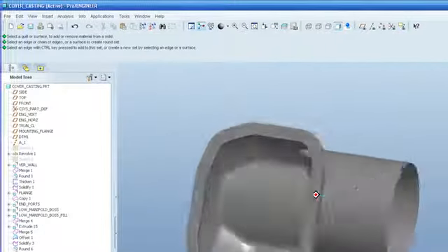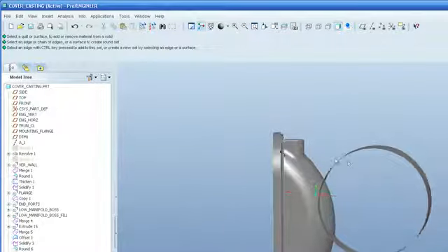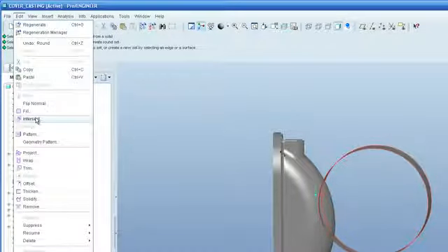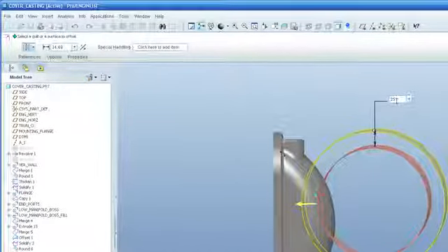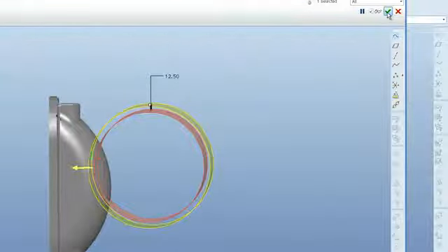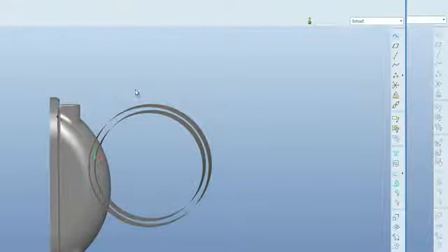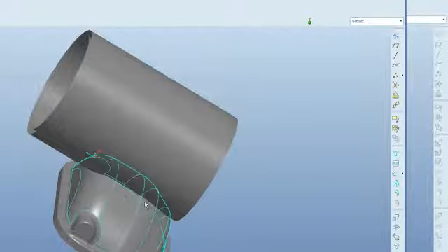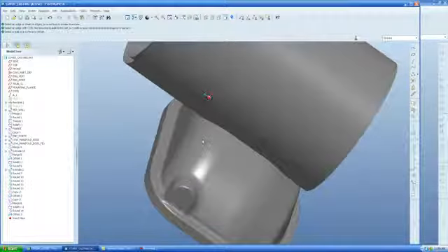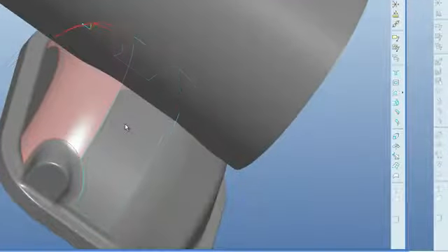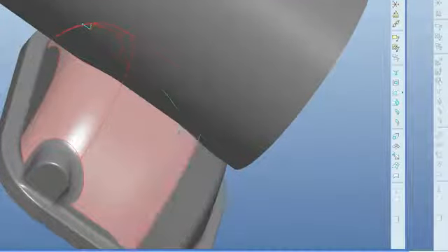So now I have the material inside my casting, but now I need to cut away a clearance for the outside of my casting. A quick and easy way again is to select the original copy that you brought in, go to Edit, go to Offset, offset the distance that you want your cut or your clearance from your tank, and now I have to select surfaces to intersect that to create another merge solidify.